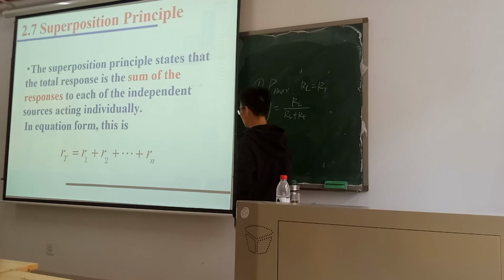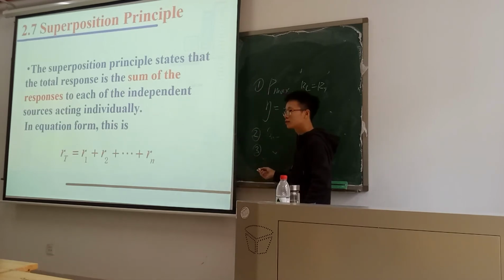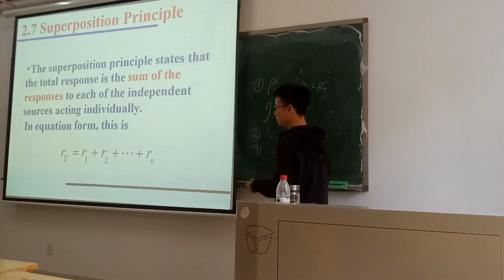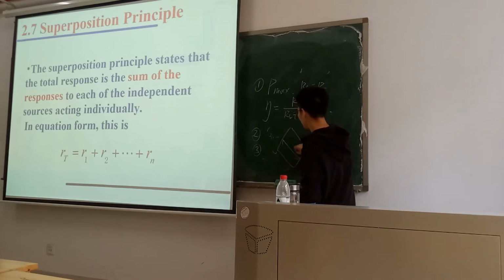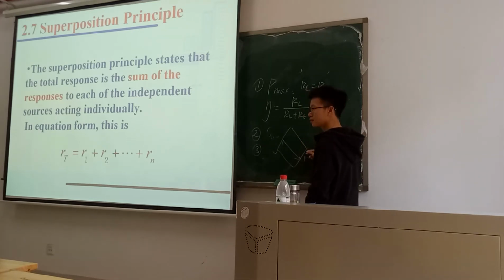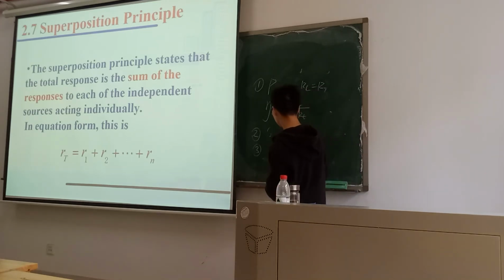And the last is the Wheatstone bridge. Calculate the Rx. You don't need to remember R1, R2, R3 or others. Just remember the opposite sides, multiply together, and we can get the Rx. So this is what we learned today.